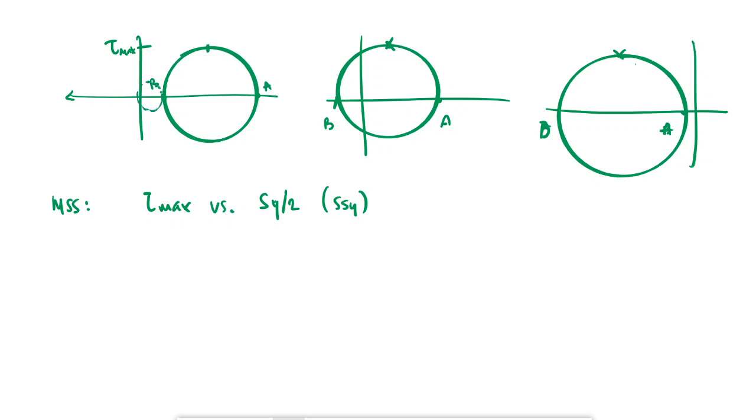For cases 1 and 3, I would have a sigma 3 equal to 0 here, and a sigma 1 equal to 0 here, right? So this would be the maximum in-plane shearing stress. But there's an overall circle that encompasses both of these, and this overall tau max is what I want to compare. So it's not this one, and it's not this one right here. It would be a higher one.